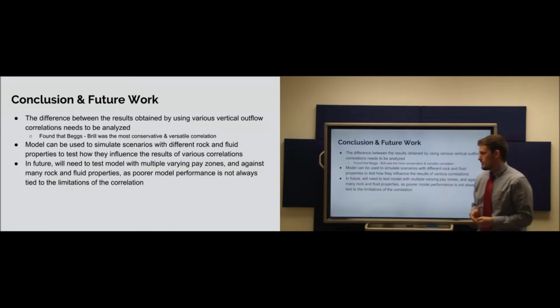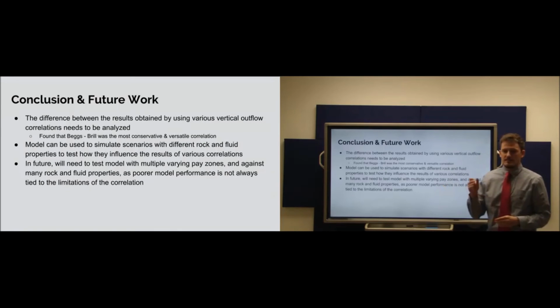And in the future, we can do those tests where we vary, say, rock compressibility or average reservoir pressure or bubble point of the oil in order to see how that would affect the worst case discharge calculations, because the flow correlations are not the only factors that affect the performance of our results.